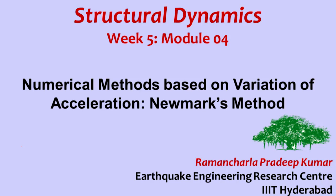Welcome to structural dynamics class. In this class we will study numerical methods based on variation of acceleration. A special application in that is Newmark's method. As you have seen in the previous class, we had discussed the central difference method. In the central difference method, we were calculating displacements at each time instant, and we converted acceleration and velocities in terms of displacements.